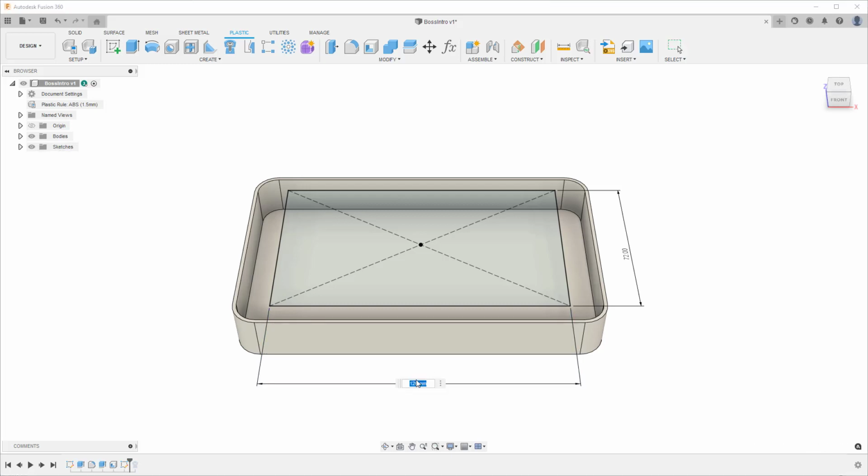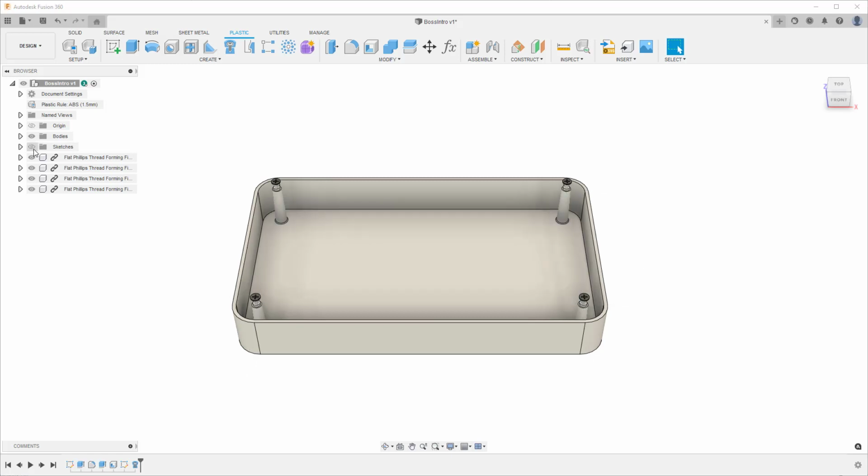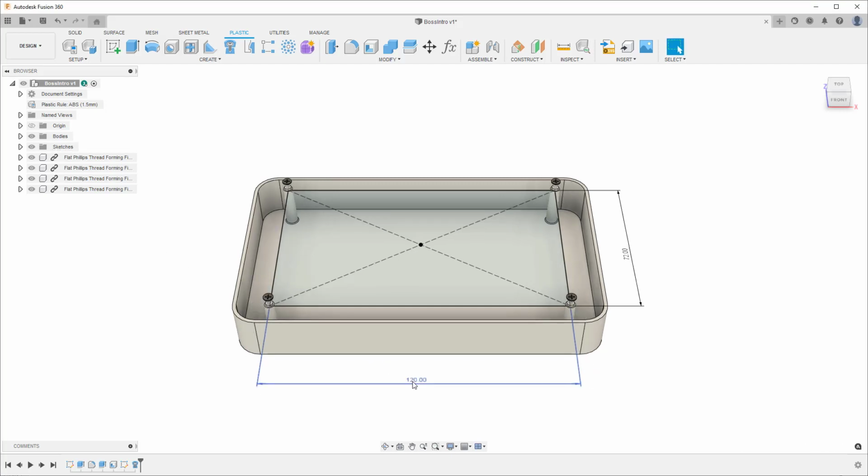You can either create points using the point command, or Fusion 360 automatically recognizes the end and center points of lines, curves, or arcs. As a best practice, you may want to create your sketch points on the parting line between the two solid bodies that will connect. And again, as the sketch feature is parametric, you can always come back and edit these sketch points at a later time.